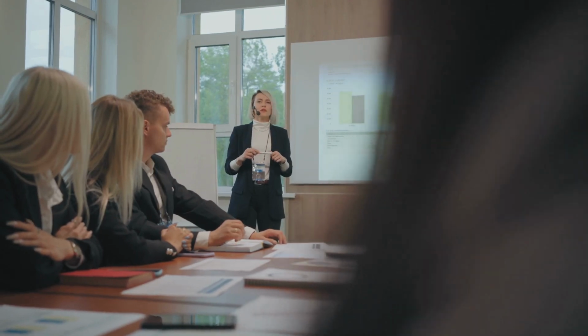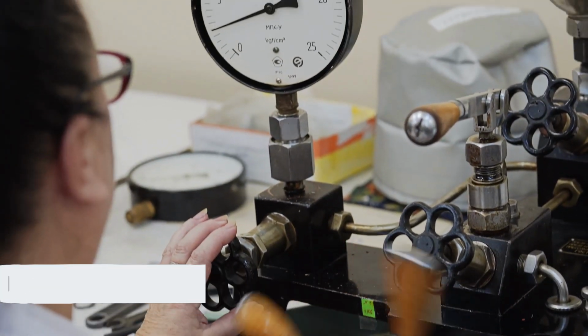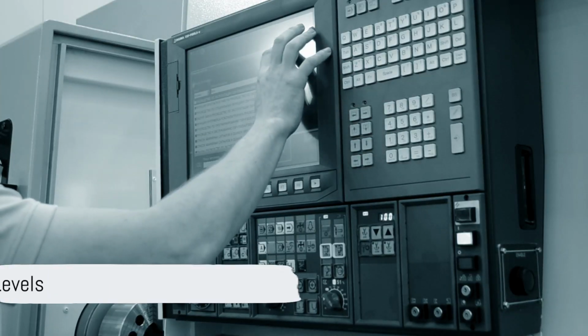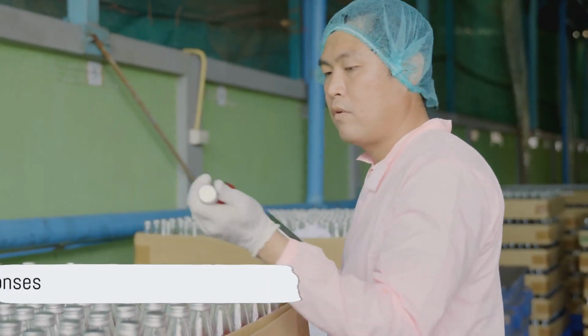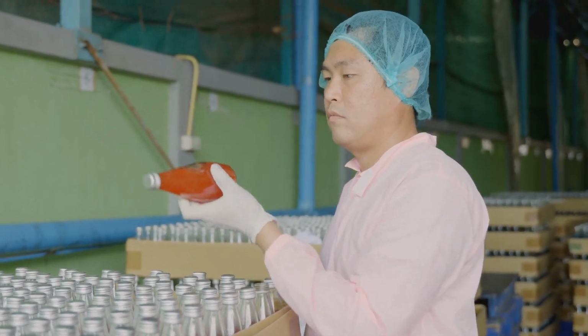Before we build a DOE, let's cover 5 core terms you'll need to understand. Factors. These are the variables you want to study. Think machine speed, temperature, or pressure. Levels. The settings you'll test for each factor. Typically low and high, though more levels are possible. Responses. The output you're measuring could be strength, weight, defect rate, or even customer satisfaction.